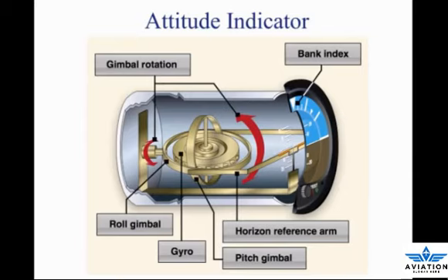The gyro in the attitude indicator is mounted in a horizontal plane and depends upon rigidity in space for its operation. The horizon bar represents the true horizon. This bar is fixed to the gyro and remains in a horizontal plane as the aircraft is pitched or banked about its lateral or longitudinal axis, indicating the attitude of the aircraft relative to the true horizon.